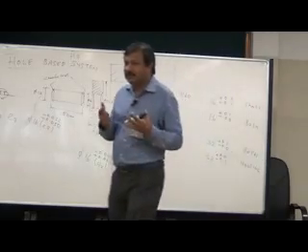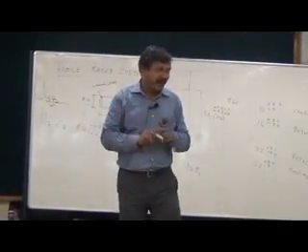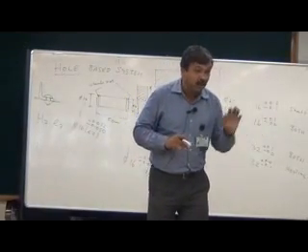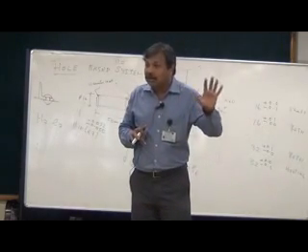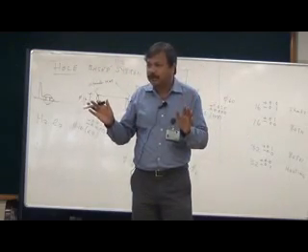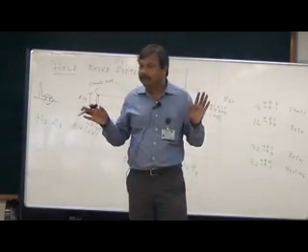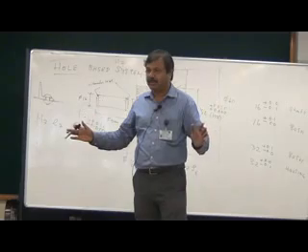So, what Taguchi asked himself was, of course, he had identified successfully the root cause of the problem. What is the root cause of the problem? The root cause of the problem is non-uniform temperature distribution. How to eradicate the root cause of the problem? Redesign a furnace with uniform temperature distribution.